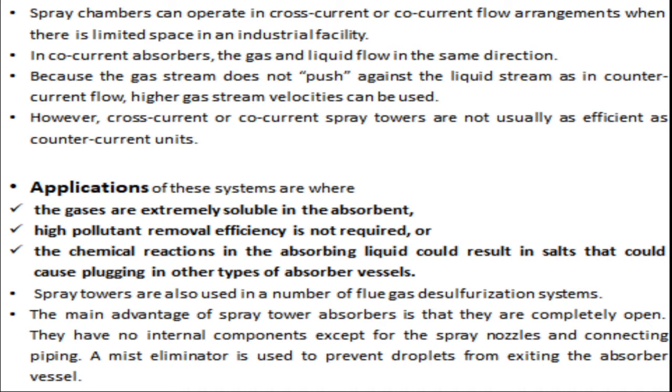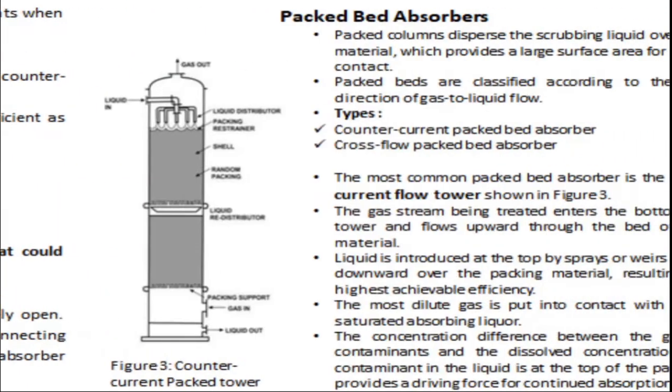Now these spray towers can be used in a number of flue gas desulfurization systems, and the advantages are that they are completely open. They have no external components except for the spray nozzles and connecting pipe.